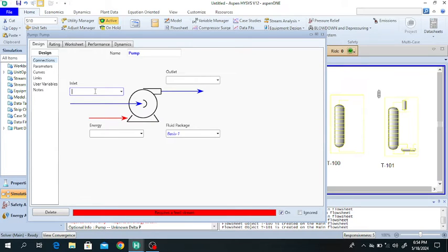For that purpose, first of all, we will pump benzene to increase its pressure. So we will take pure benzene. This is the benzene inlet, and it will pass through a pump to increase its pressure. After that, we will heat the benzene to increase its temperature, because the reaction between benzene and oxygen to produce maleic anhydride is in the gaseous phase and it is an exothermic reaction.